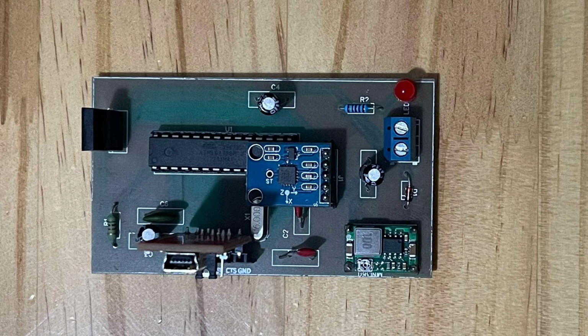Next, we added the ADXL335 sensor, which is going to be detecting vibrations in three axes, X, Y, and Z. And then we connected it using a pin header so we can plug it or remove it easily. We also added a 3.3 volt regulator, the LD33CV, because our sensor works on 3.3 volts. And to power the board, we used a mini 316 voltage regulator to step down the input voltage to 5 volts, and we added several capacitors to stabilize our power.